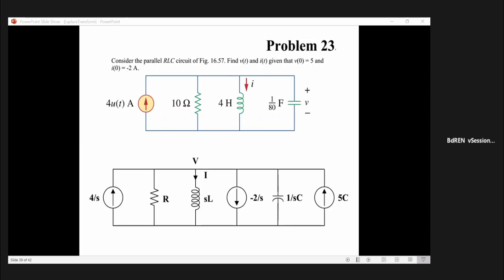The second is that if we can derive the input-output relationship in the time domain, then you can apply the Laplace transform to the differential equation, and easily find the total response of your system, the zero state response and the zero input response also. And the third and more widely used technique is to convert your network into the Laplace domain by element-wise transformation, which we have illustrated in our earlier classes.